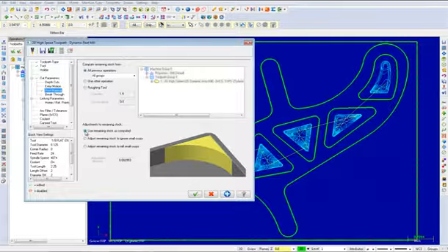Adjust remaining stock to ignore small cusps is used to set the adjustment distance to reduce the stock model. Mastercam outputs cuts that engage large amounts of material. And finally, adjust remaining stock to mill small cusps is used to set the adjustment distance to expand the stock model. You can now select the OK button to generate the toolpath.